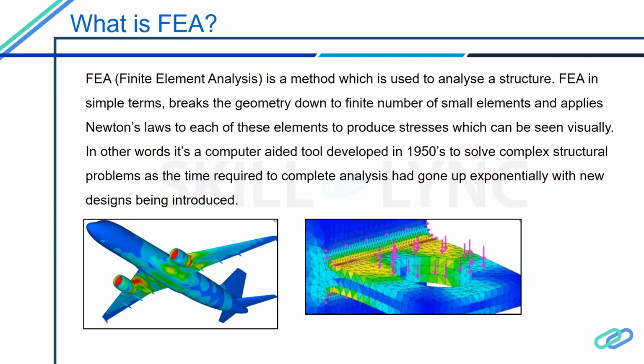Whereas, as I said before, if you have a complex galley structure, or a wing structure, or for example a fuselage structure, you can't use an analytical method and do everything by hand calculation. It's not that simple, and it's practically not possible. So you have to use the finite element method, or FEM, which is a numerical method, and it saves computing time.